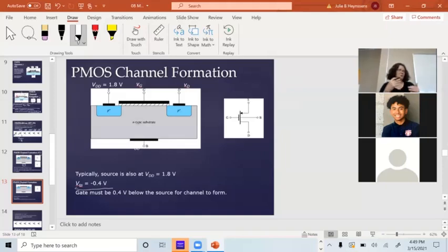As the device dimensions have decreased, so have those threshold voltages. So now you're talking about 1 to 2 tenths of a volt. They're just smaller numbers. If you understand how all this works, changing the numbers isn't that big of a deal. A lot of the time it's just changing your SPICE deck. We'll talk about that.